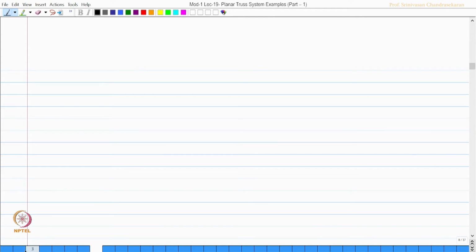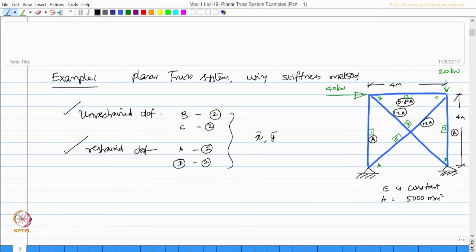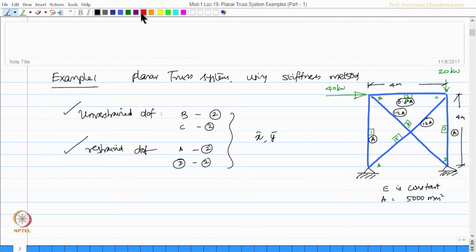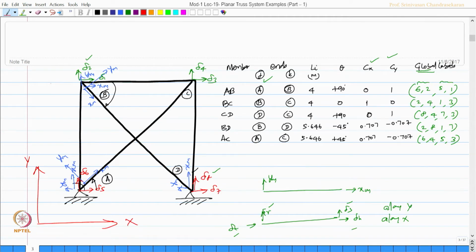So, looking at this example, the joint forces are applied at degrees of freedom. You can see here delta 1, the forces are applied at 40 and 20 here. This is 40 kilonewton and this is 20 kilonewton. So, now the joint load vector at delta 1 you get 40, okay, and delta 2 is 0, delta 3 is 0, delta 4 is again 20.